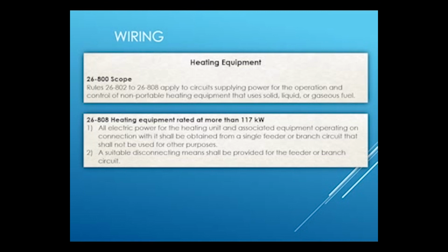Our control wiring is supplied from an integral Class 2 transformer. Therefore, Section 16 in our codebook applies. The transformer is supplied from the manufacturer, and it is sized to handle all the low voltage components. This is in reference to the VA rating of the transformer. We need to make sure that we follow manufacturer specs in order to avoid any overloading in case new components are being added to the system.